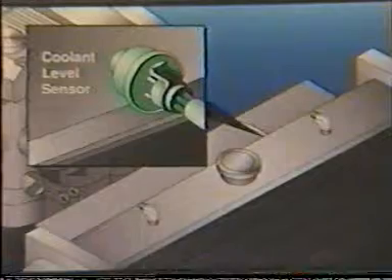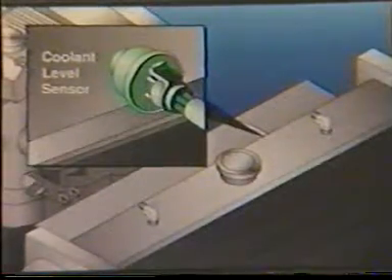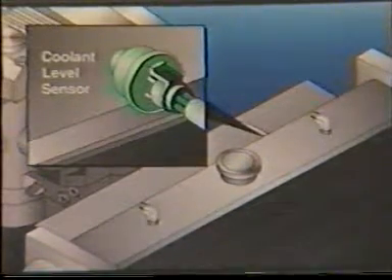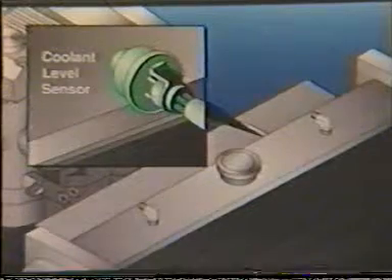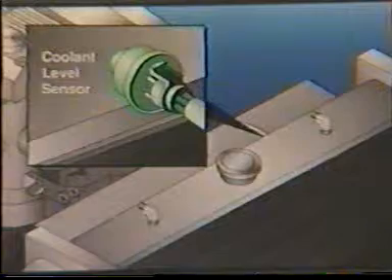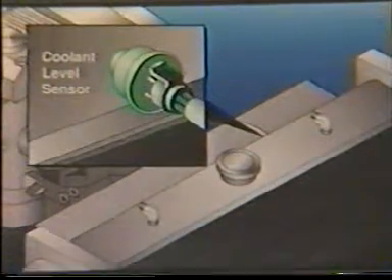The coolant level switch monitors the coolant level in the radiator top tank. If the fluid level drops below a predetermined point, the switch will open, indicating a low fluid level to the ECM. The information this sensor obtains is utilized by the ECM to make decisions for engine protection.